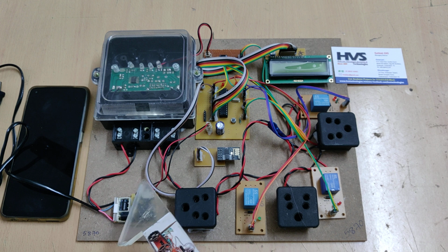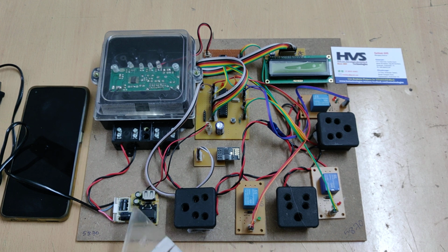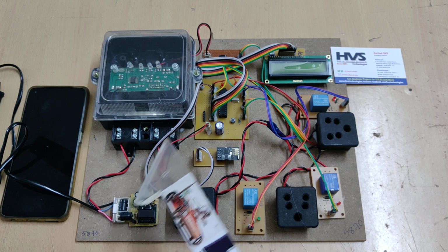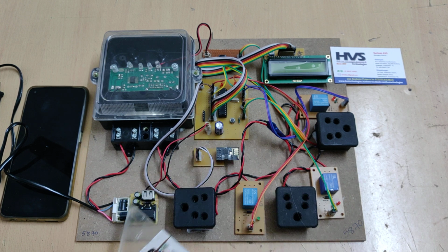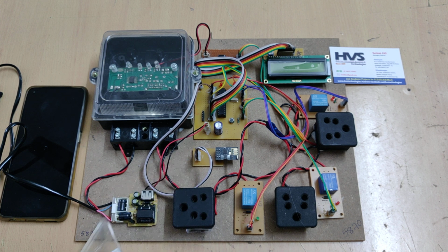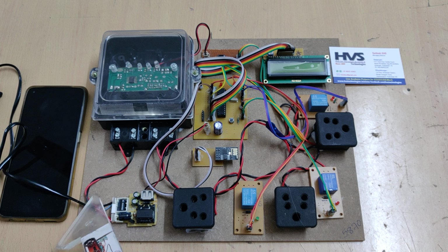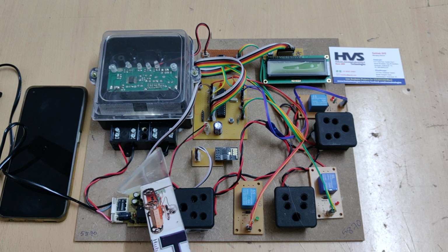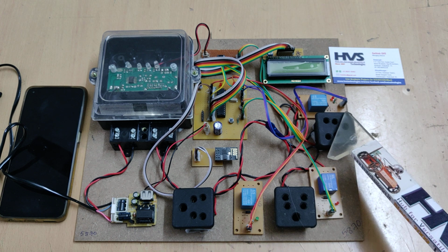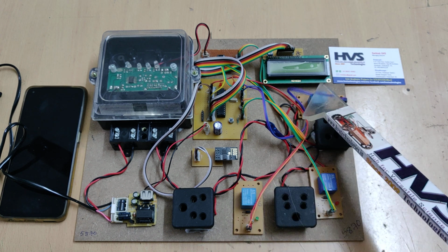Filtration removes the pulses and provides a constant 12 volts DC output, but we need 5 volts as the operating voltage is 5 volts. For that purpose the 7805 is placed, and we get a constant 5 volts DC output. Parallelly we are providing the same 230 volts input to this energy meter, and its output is given as input to these three sockets through the electromagnetic relays.